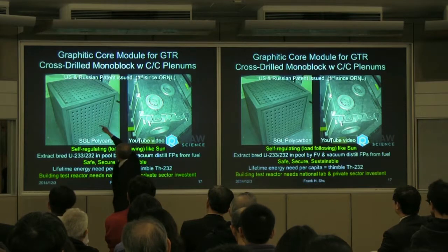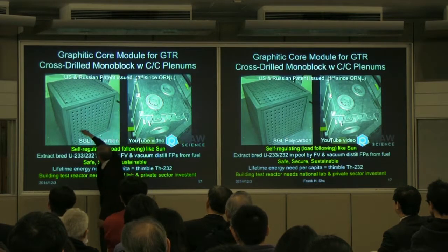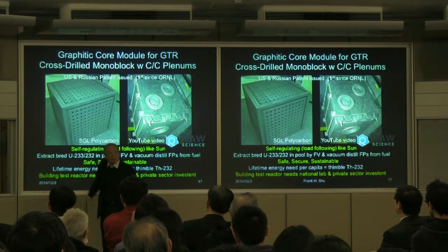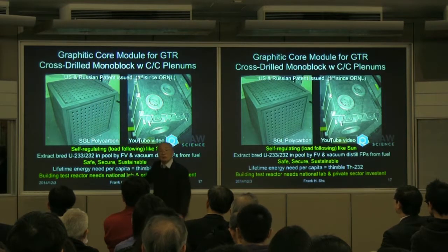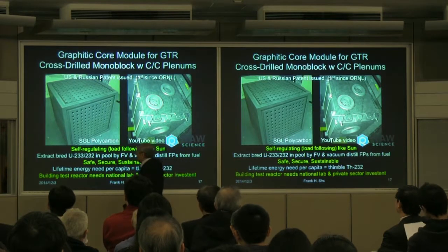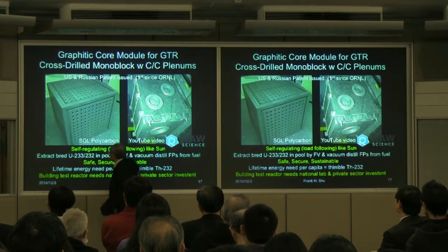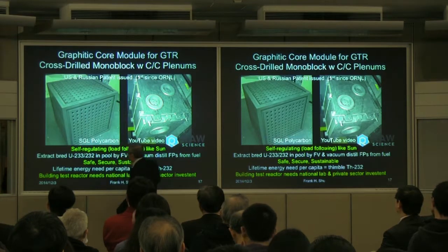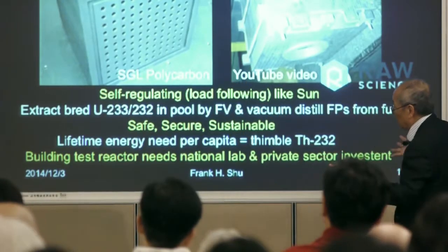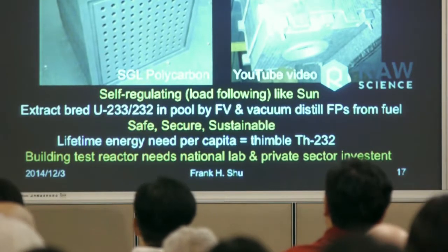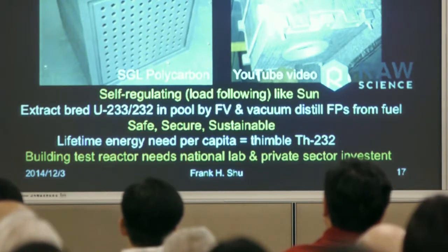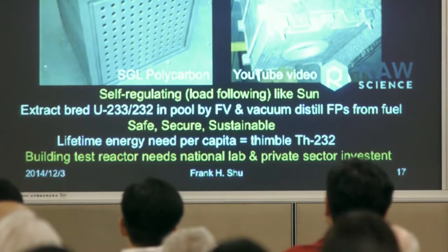So here we send fuel salt. When it meets the bottom, it turns up, it goes back up. So it just circulates as a pump, as a cycle. So we don't let it do anything other than transfer heat to the blanket salt, which carries the thorium. As it's carried into this reaction zone, it's irradiated with neutrons, so you also turn it into new fuel, which then you use chemistry to put into the fuel salt channels.